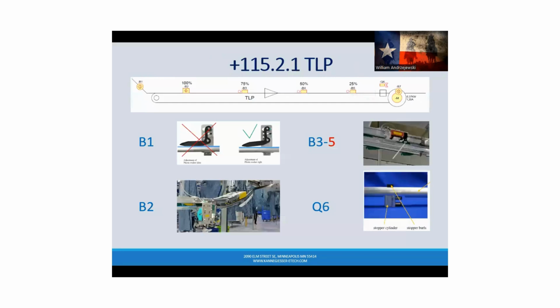The other uniqueness of the W2 system is we know we've got these X67 modules labeled all the way around. The X67 modules match the conveyor number. So the first X67 module for conveyor 115 is going to be labeled 115 2 TAC 1 K0. Okay, Ks are going to be your X67 modules.